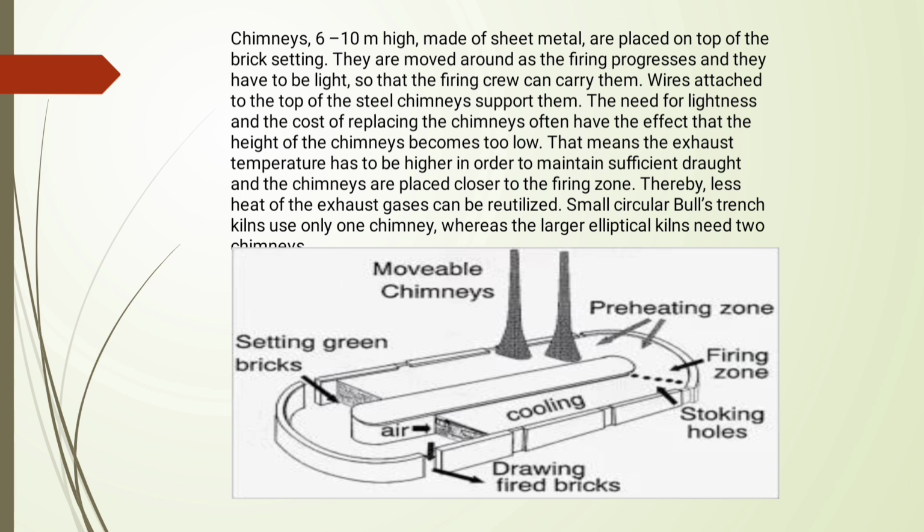When the section has been burned, the flue holes are closed and it is allowed to cool down gradually. The fire is now advanced to the next section and the chimneys are also moved forward. A tentative arrangement for different sections may be as follows.